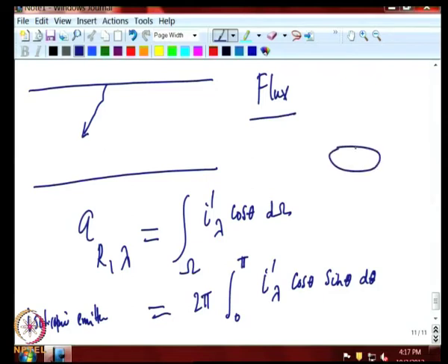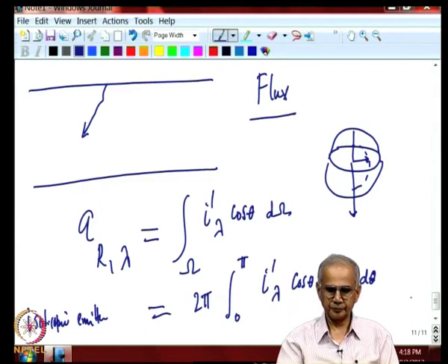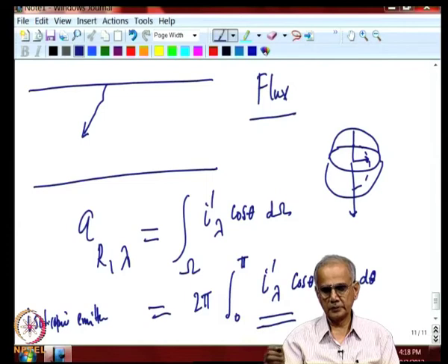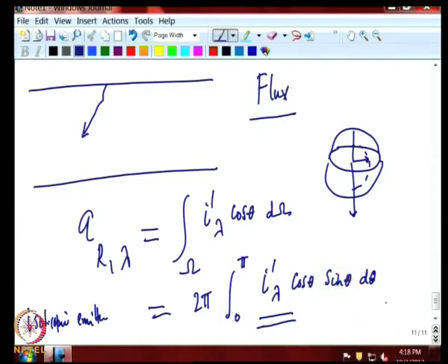You have a plane and you have to integrate over this and also this. So, integration from 0 to pi covers, in this plane parallel situation, all intensity going upwards and downwards. Once you solve for the directional spectral intensity by solving those equations, you then plug it into this expression to get the flux, and finally, this is what matters, q r lambda and its derivative.